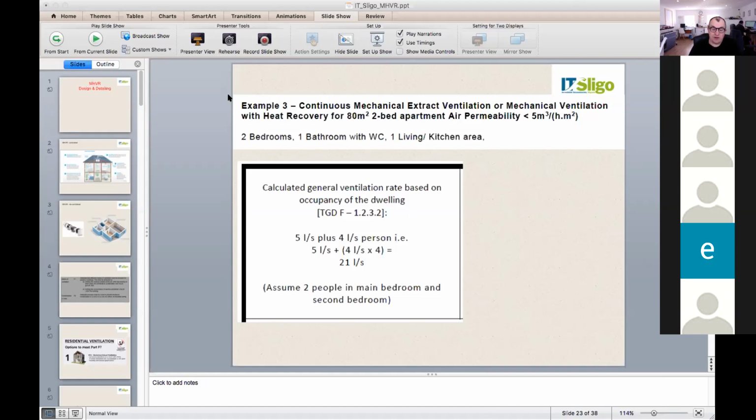That's a centralized unit, where there's a central unit up in the attic and it's doing what I just said. You can also have a decentralized system where you have small units such as this in the rooms, and each unit is working individually to bring in the lovely clean air, extract the heat, and push the new warm air back into the room. And any of the hot rooms, like the bathrooms, it's also taking out the moisture out